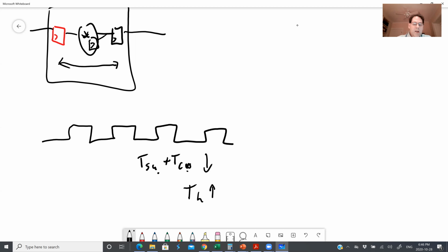In the hold time, what you can do is, so you've got some paths that are too fast. You've got a register, not much logic feeding another register, and you've got to worry this pulse latch doesn't have as good a hold time, so maybe you get a violation. This path is too fast, and data runs through.